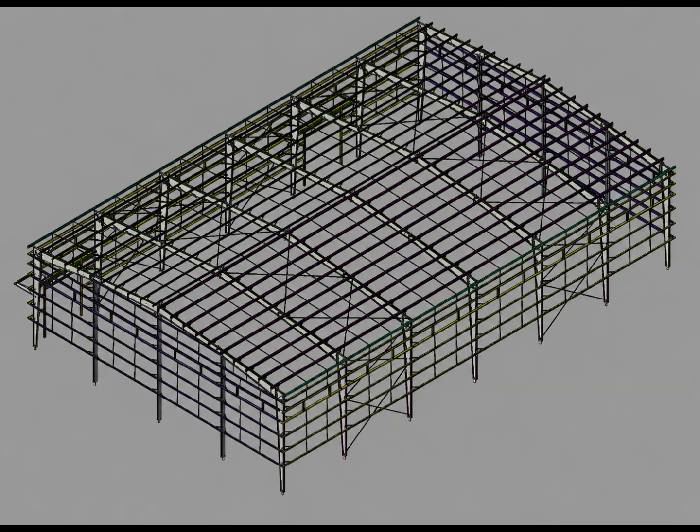Now think about the relationship between the drawings and this model. The plan tells us where the members are located horizontally. The elevation tells us how the members are arranged vertically. The connection details tell us how individual members are connected. And the 3D model brings all of these pieces together into one spatial representation. This is why learning to read both drawings and 3D models is extremely valuable for a PEB detailer or structural draftsman.